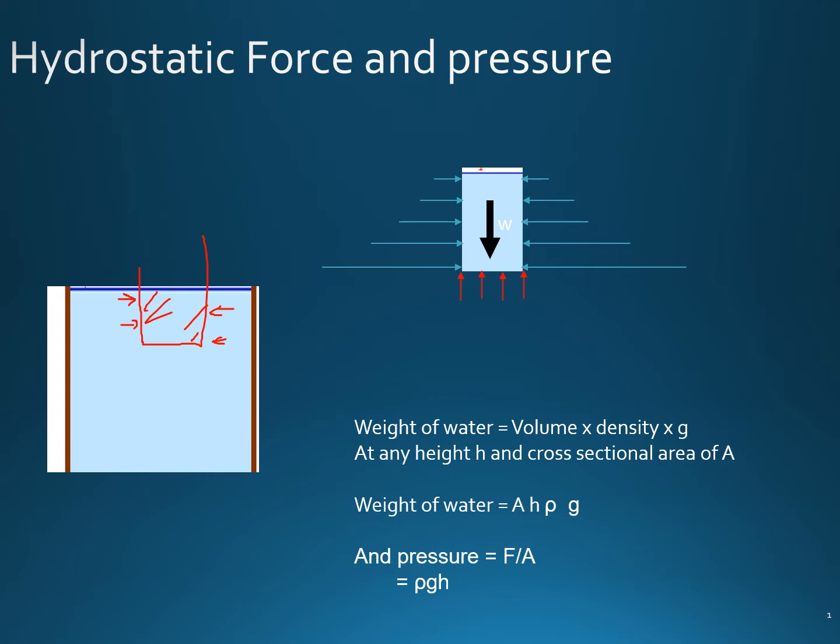We all know that the free body diagram is a diagram with replacement of the supports on the body when it was in its original position. So this small column of the water is supported from three different directions in this two-dimensional plane: from the x direction, two sides, and from the bottom. At the top, it is exposed to the atmosphere, so we don't need to draw it because there was no force. Actually, there was the atmospheric pressure, but we just ignored it.